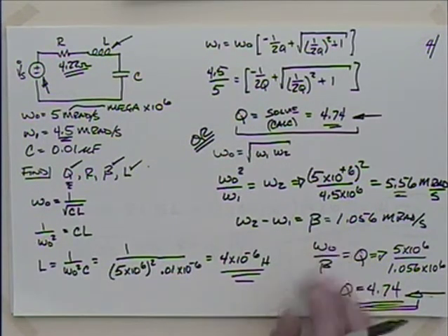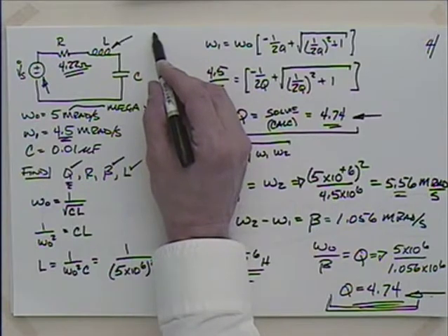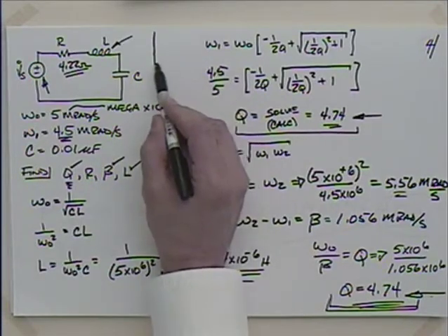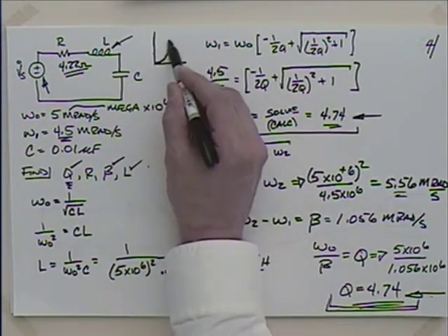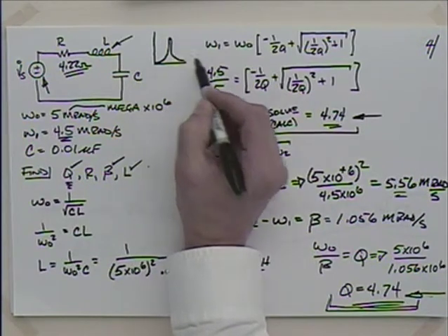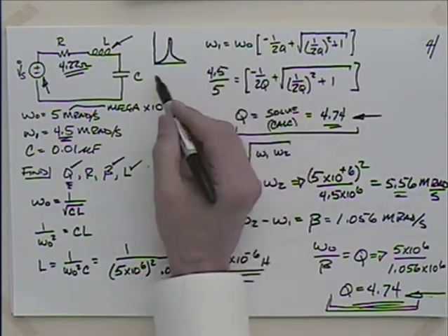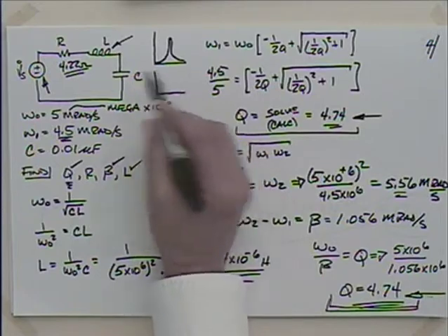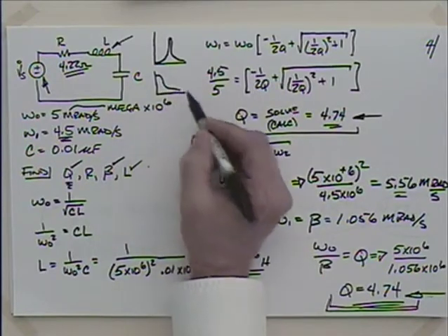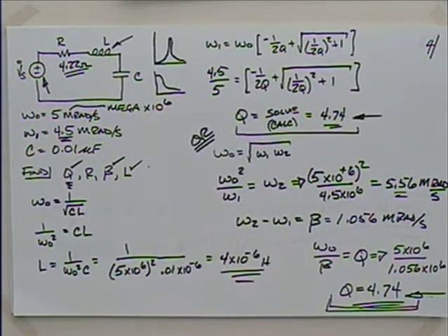Yeah. So that's why a lot of times students next term, we'll see this again, they'll have this really great bandpass filter designed. They get down to lab, they set it up, turns into a low-pass filter. It's because they have way too much resistance. So that'll give us something to worry about and work on next term.